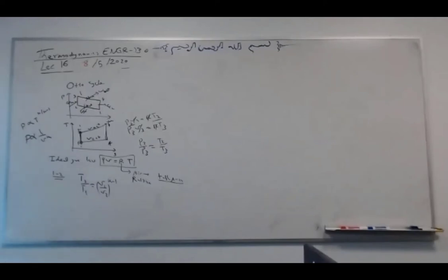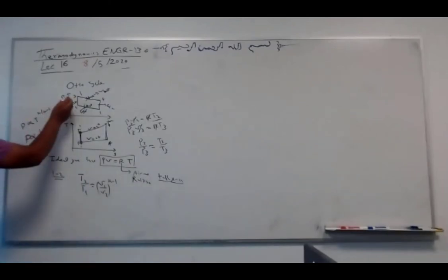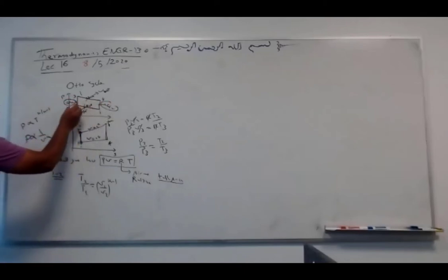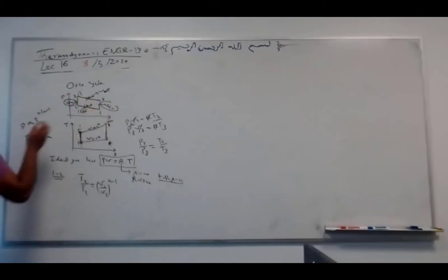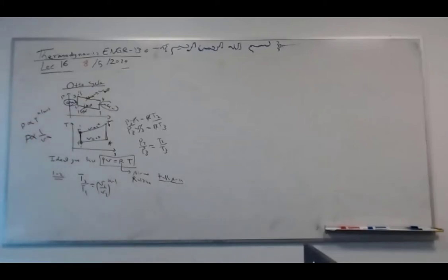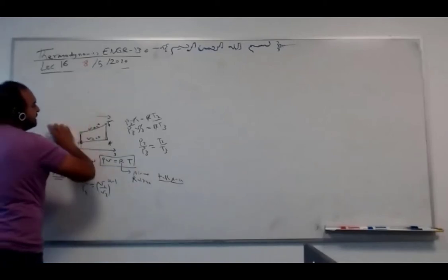The whole idea here is that we have compression, then the burning, with heat in and heat out at constant volume. Very clear here, constant volume. This is the Otto cycle: the heat addition and heat rejection were at constant volume. Let's now talk about the next section, which is 9.6.